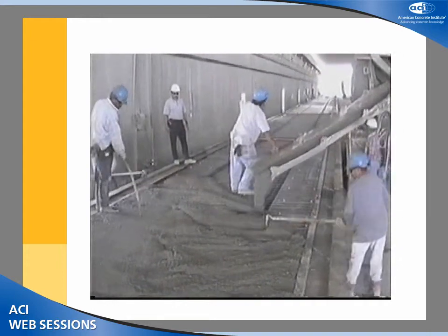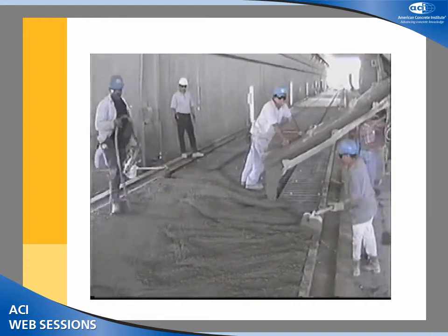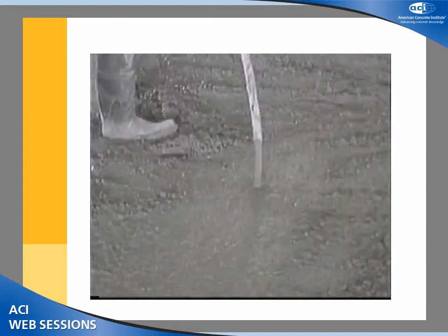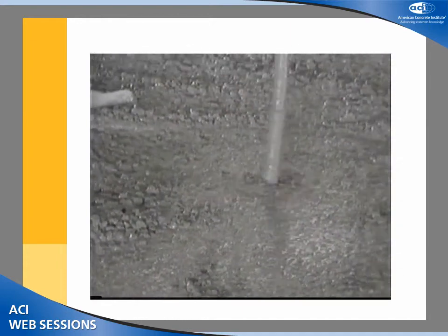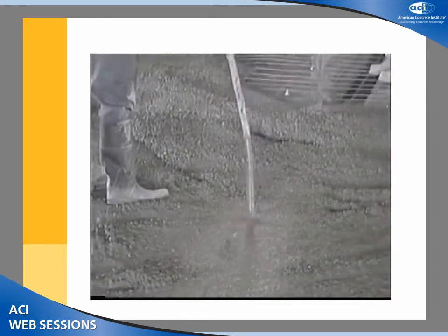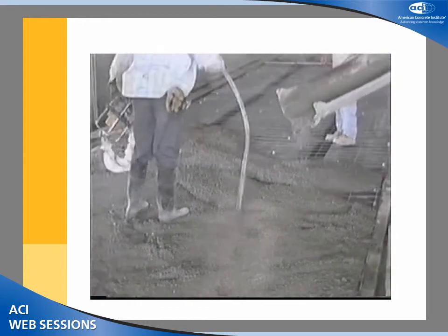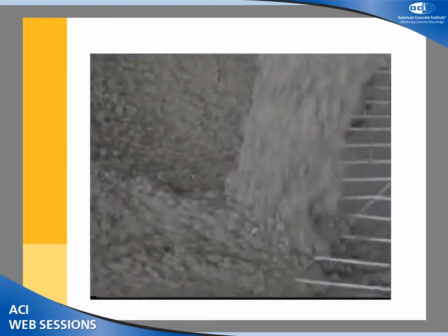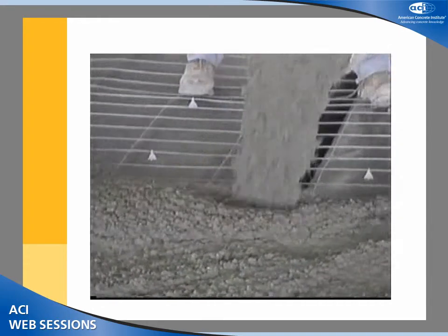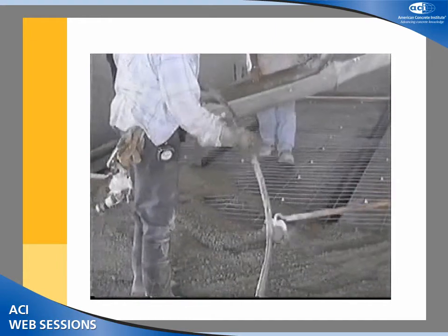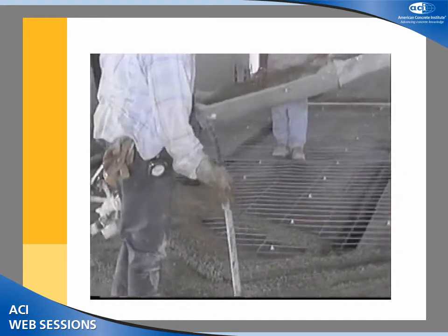You've got about 5-6 guys trying to place this material, and a lot of people sitting and waiting for the next job. You definitely have the vibrator going, trying to help place the concrete. It's a pretty decent fluid mix, but you can see there's a lot of difficulty in trying to push the material out where it needs to go. And in the next part of this video, you can see the striking difference between this concrete and the SCC.